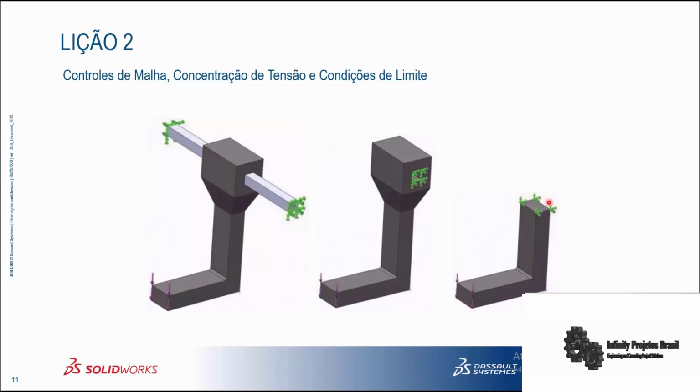There are boundary conditions because then I can define simplifications for my model. For example, if I leave my model like this, the bar, and apply internal fixings here, maybe it would be easier. Or the same thing we did before, working only with the model in the lathe and leaving it fully fixed on the top face like this. We saw that as we simplify, we gain a lot of computational time.